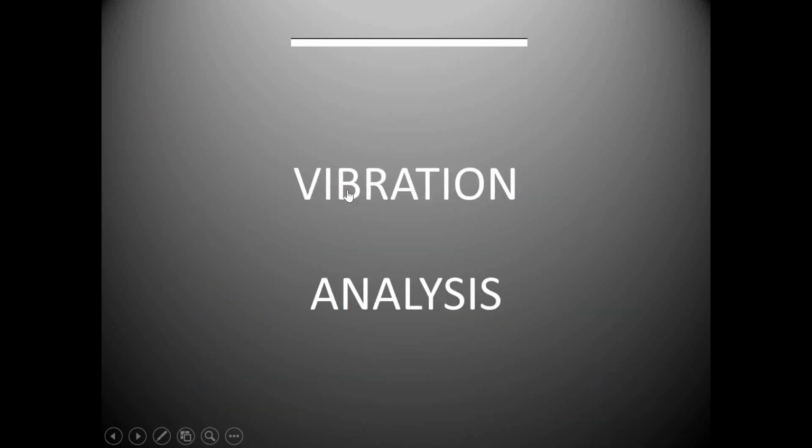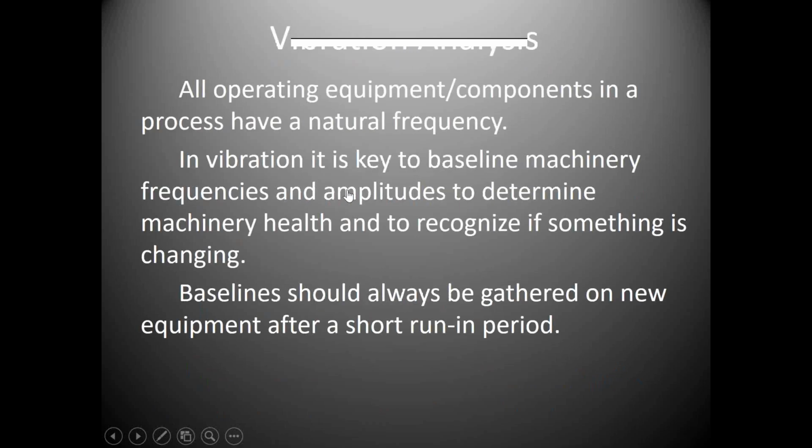Now, another technology here, vibration analysis. Sometimes we hire vibration technicians, and we're looking at their data, not understanding what they're doing, but this technology, operated by a trained technician, operated in the right way, finds a lot more failures than any of the other technologies. It gives us more details about them. But one of the things you have to remember about vibration analysis is every component in your plant has some natural frequency. We'll look at a slide here in a second so you understand what I'm talking about.